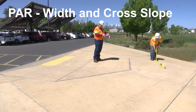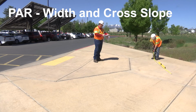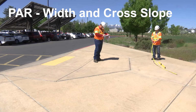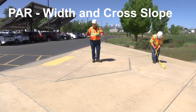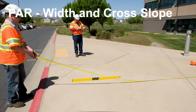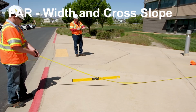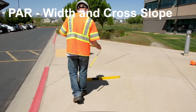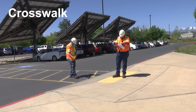We have a cross slope of 0.8% and a width of 9 feet. And lastly, off to the right, we have 16 feet there and a cross slope of 1.7%. So we are good.